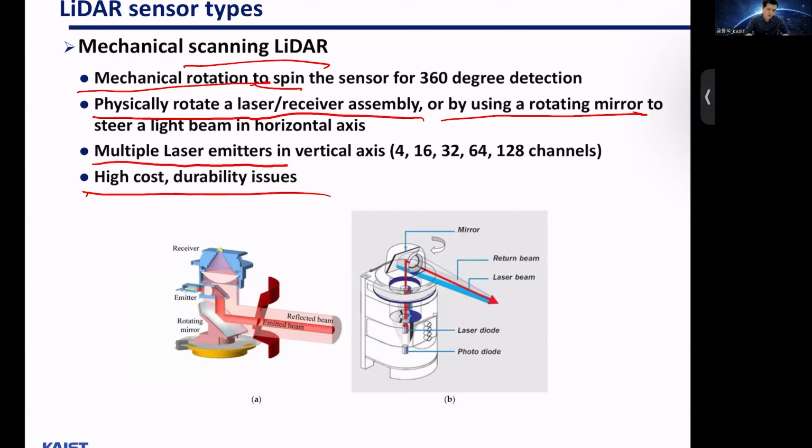You may have to go off-road, and under these harsh conditions, LiDAR can be quite a sensitive sensor to use because of its highly accurate nature, which requires calibration. So if something gets misaligned, then your sensor output can easily give wrong information.